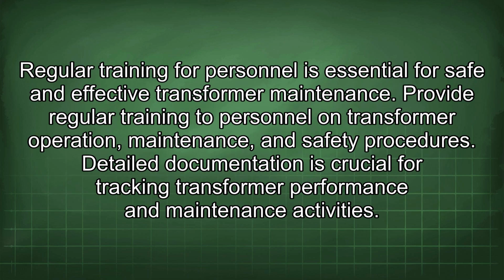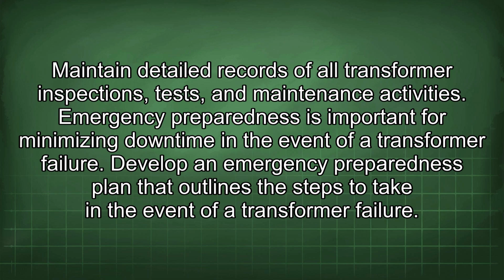Regular training for personnel is essential for safe and effective transformer maintenance. Provide regular training to personnel on transformer operation, maintenance, and safety procedures. Detailed documentation is crucial for tracking transformer performance and maintenance activities. Maintain detailed records of all transformer inspections, tests, and maintenance activities.